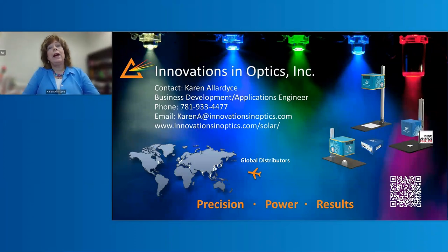AM 1.5G is the terrestrial reference spectrum. And the difference between those two is quite significant when you're designing a solar simulator, because AM0 has both a higher irradiance overall and also none of the absorption dips that you experience in the AM 1.5G reference spectrum, which is the terrestrial version.